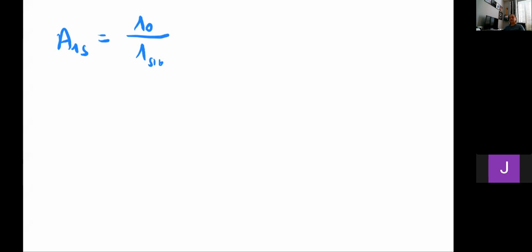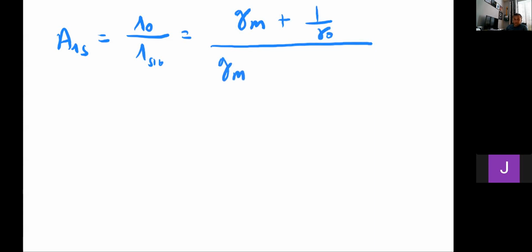and what happens is that there is a current division that happens because of the transconductances of the transistors, all the while from that common source through the common gate to the load. Okay? And then that is going to be GM plus 1 over RO, so your basic current division, so that is what we're seeing at the source of the common gate amplifier.